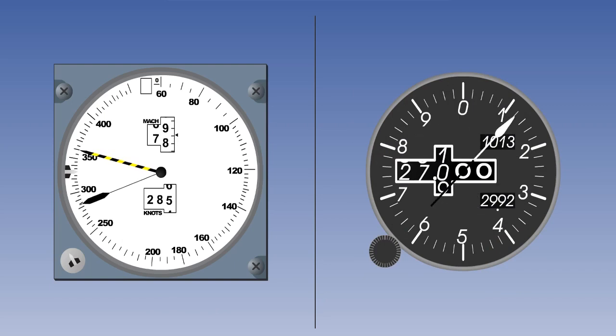As the aeroplane climbs from 24,000 to 29,000 feet, then MMO becomes the limiting factor, and this is manifested by the barber's pole reducing in value. The reason it does this is that as altitude increases, when climbing at a constant indicated airspeed, MMO, when expressed as an indicated airspeed, decreases.